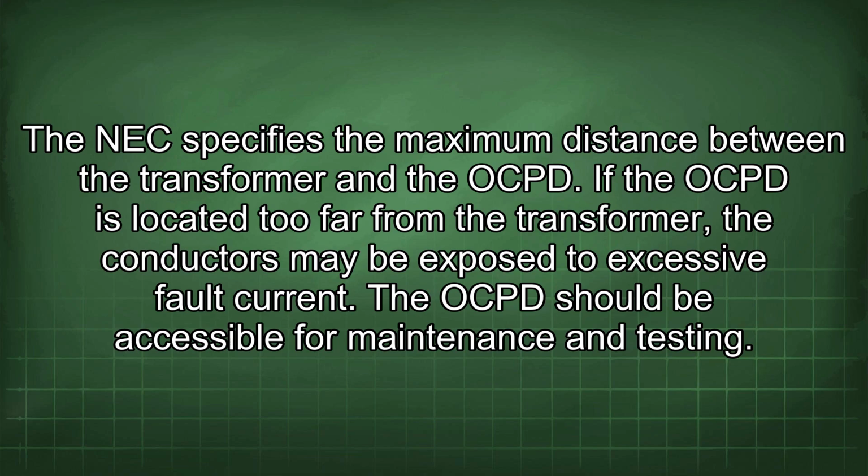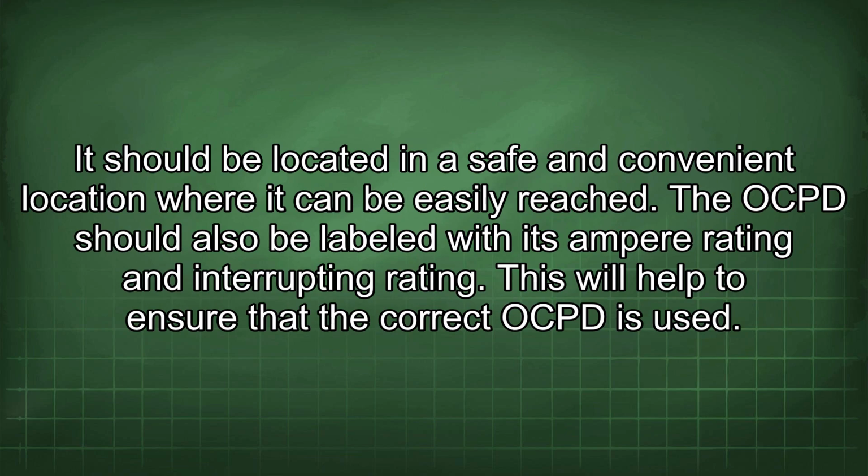The OCPD should be accessible for maintenance and testing. It should be located in a safe and convenient location where it can be easily reached. The OCPD should also be labeled with its ampere rating and interrupting rating. This will help to ensure that the correct OCPD is used.